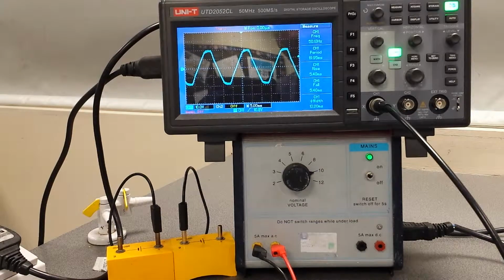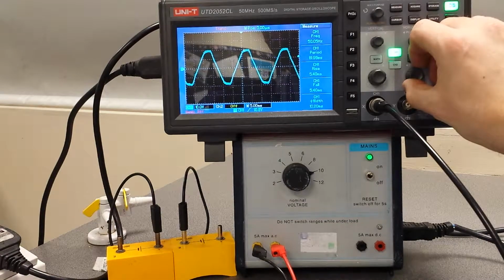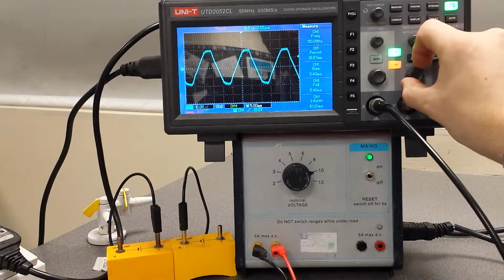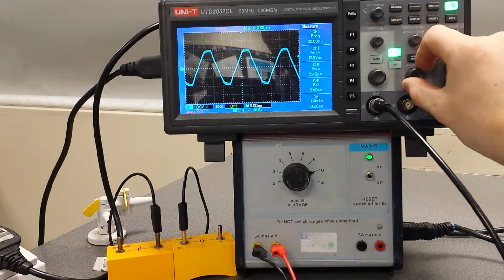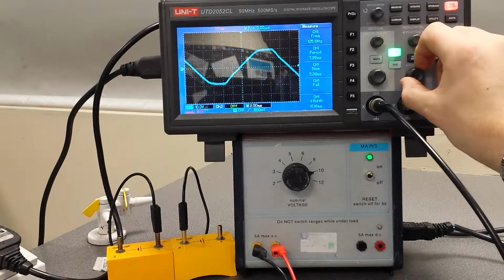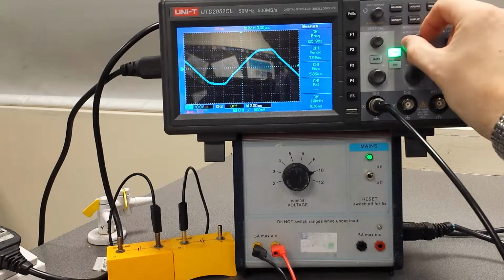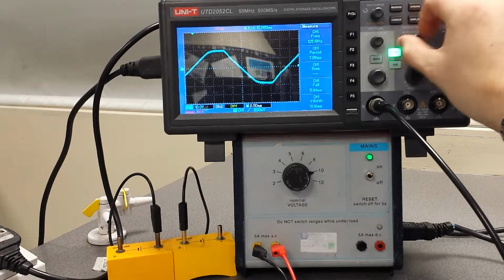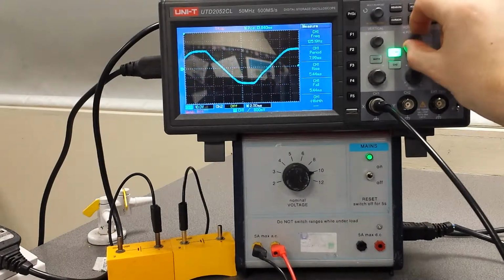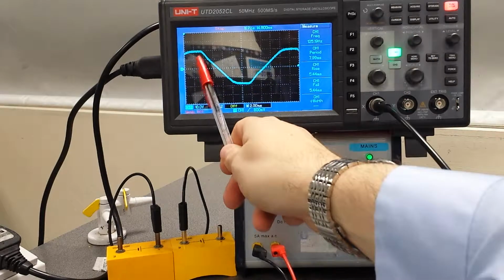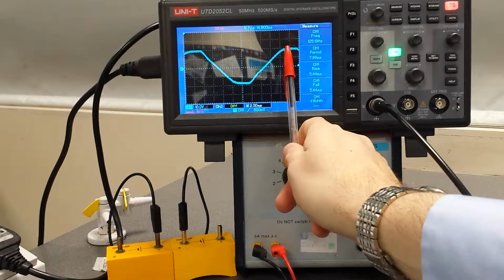Now there's something quite clever we can do with our trace. Now I'm just going to alter my scale slightly. Let's freeze it actually, which is a clever thing you can do with these digital ones. So hold on, we've autoed it. We'll stop it. We'll scale it. Now we can move it around. And now then, what I'm trying to find is a whole peak. There. So I've got peak to peak. So I've got a position now where I've got from here all the way to here.